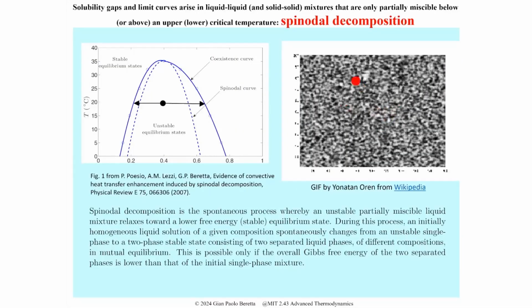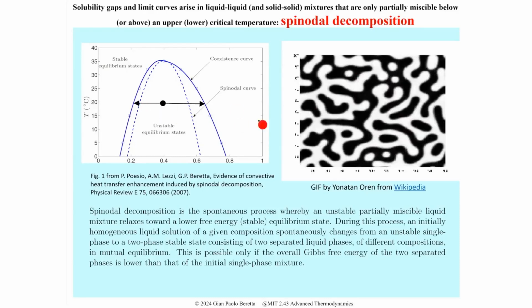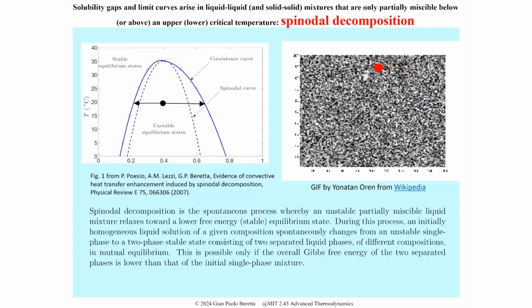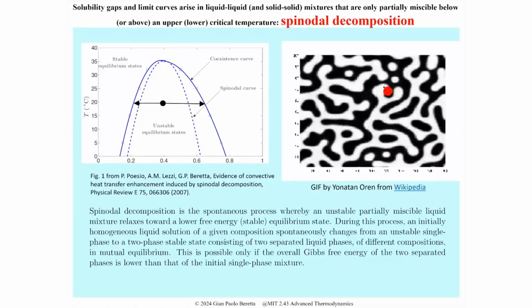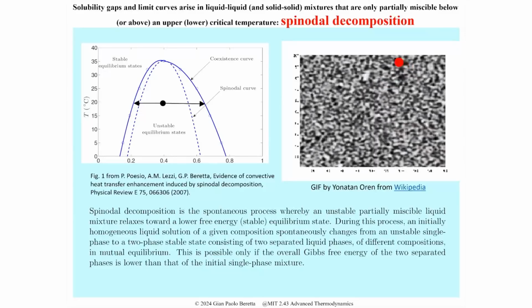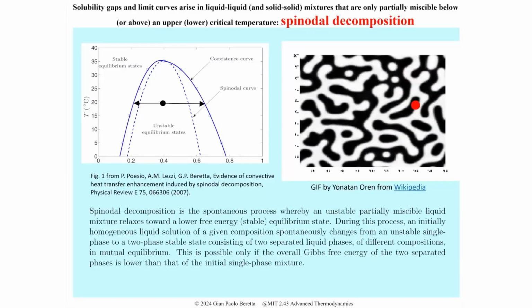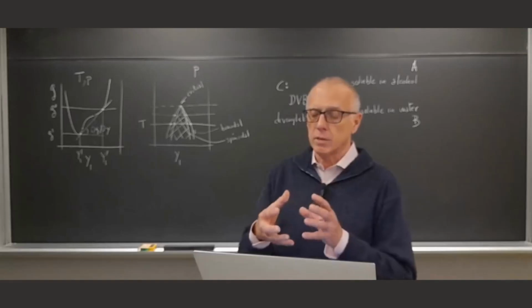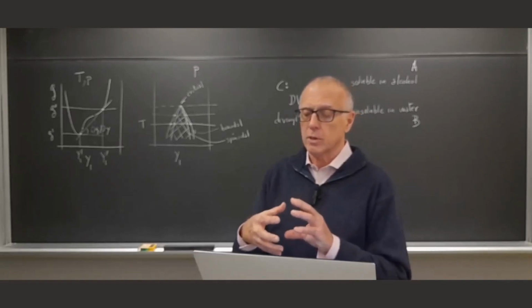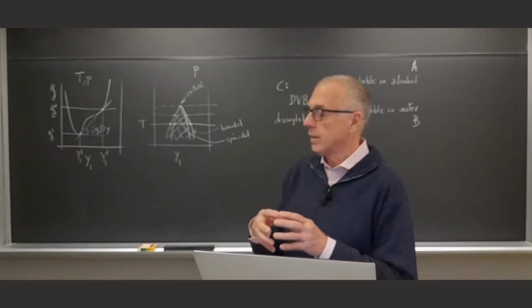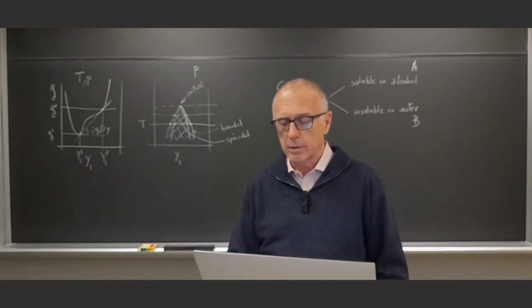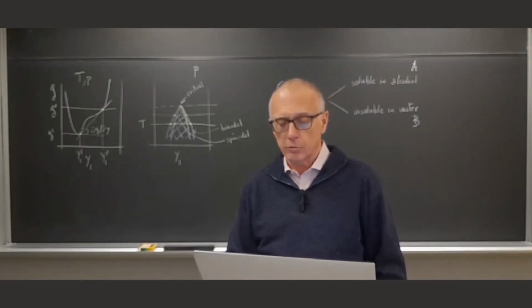But if you use a situation like this one, generated by a spinodal decomposition, and you freeze, then because there is a path in which the dark phase becomes solid and the liquid in the white phase can drain away, you produce a porous material with a high surface area, which can be used for enhancing or studying biological processes, but also for other applications in which you need a lot of surface for things to happen, like catalysts.